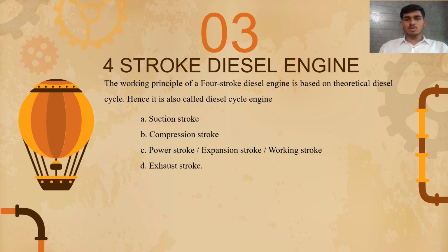So now the four-stroke diesel engine. The working principle of the four-stroke diesel engine is based on the theoretical diesel cycle. Hence it is called a diesel cycle engine. The four strokes of the four-stroke diesel engine are suction stroke, compression stroke, power stroke or expansion stroke or working stroke, and finally exhaust stroke.